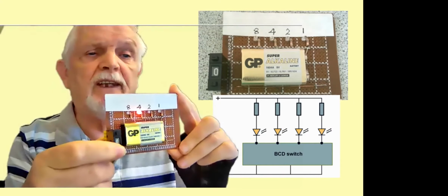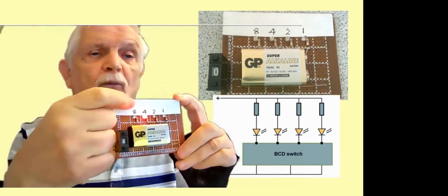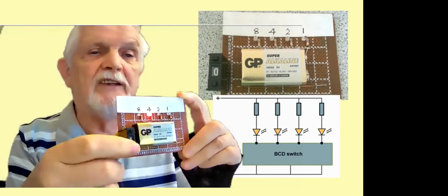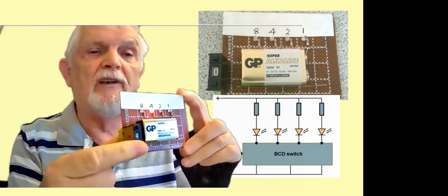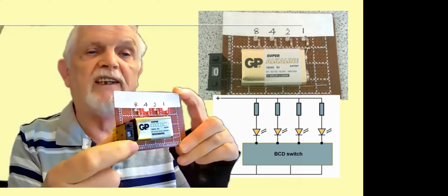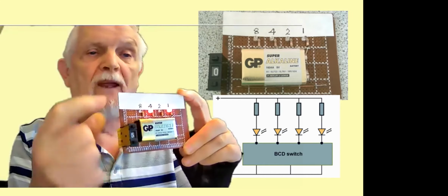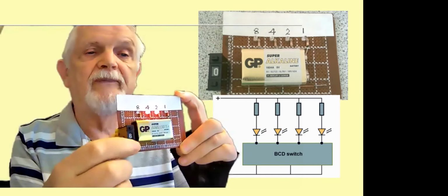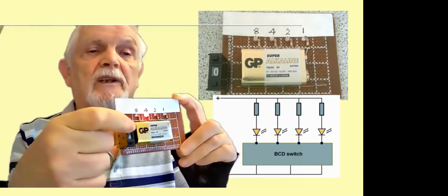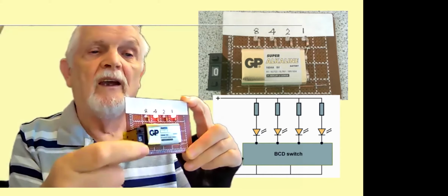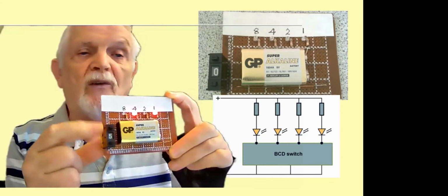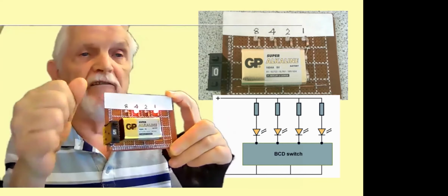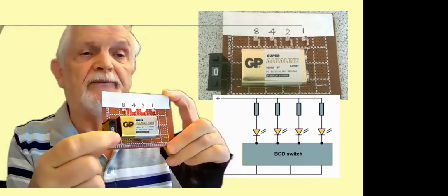So you'll see there, I've got the 1, 2, 4, 8 right along. So 4 is lit up. So there's one lot of 4, nothing else. Press it again. I've got one lot of 4 and one lot of 1. So I've got 5. And you can go up and down. And that would be on a panel to let you set values, but just by pressing buttons.